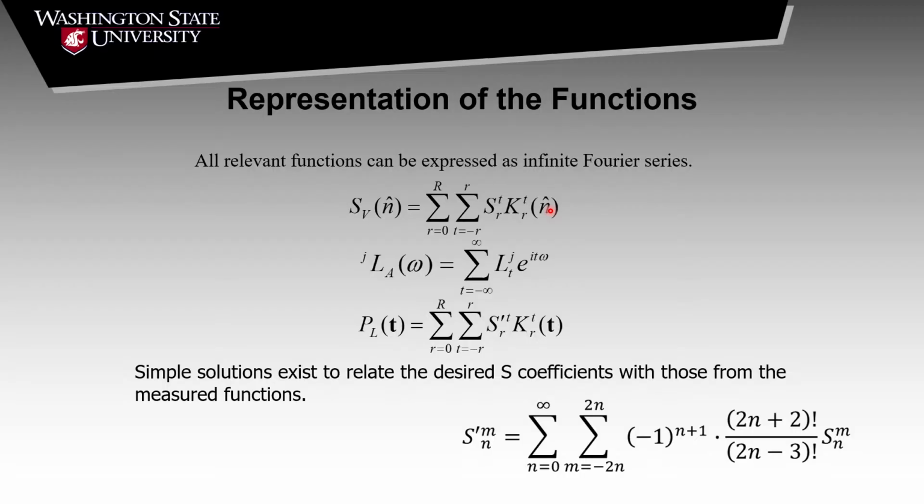But then I go back to that fundamental equation of stereology that I showed you before, that integral equation where you have a t dot n and you're integrating over the space of n. And once I do that, I put in all these Fourier expansions. This is the solution I get, right? Where my S coefficients are known in terms of my S prime coefficients.